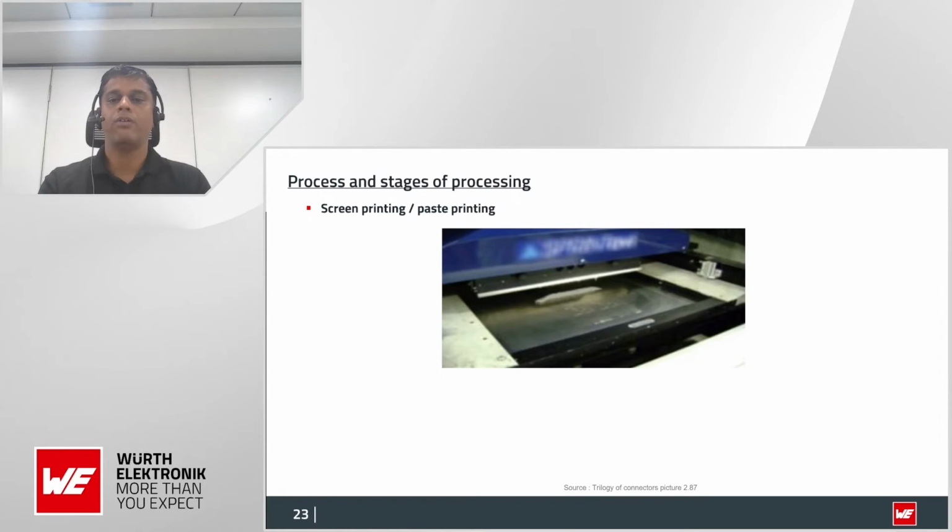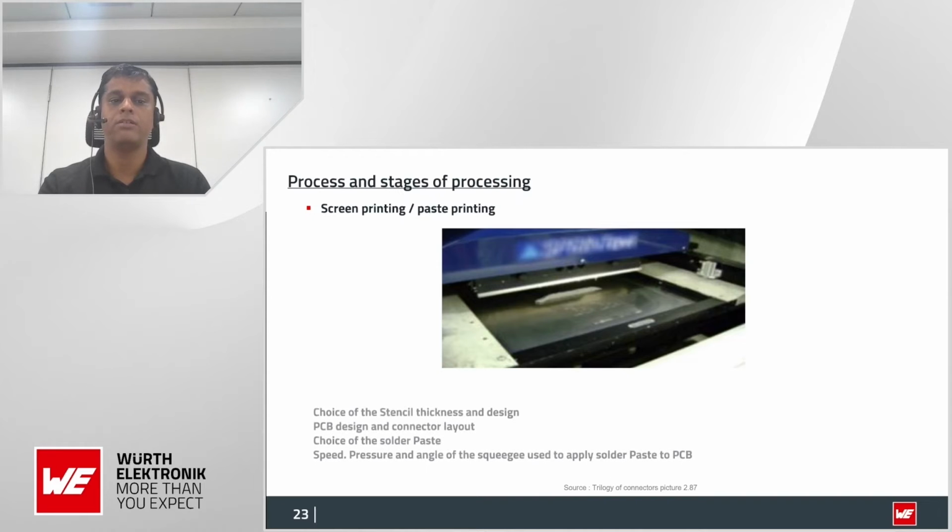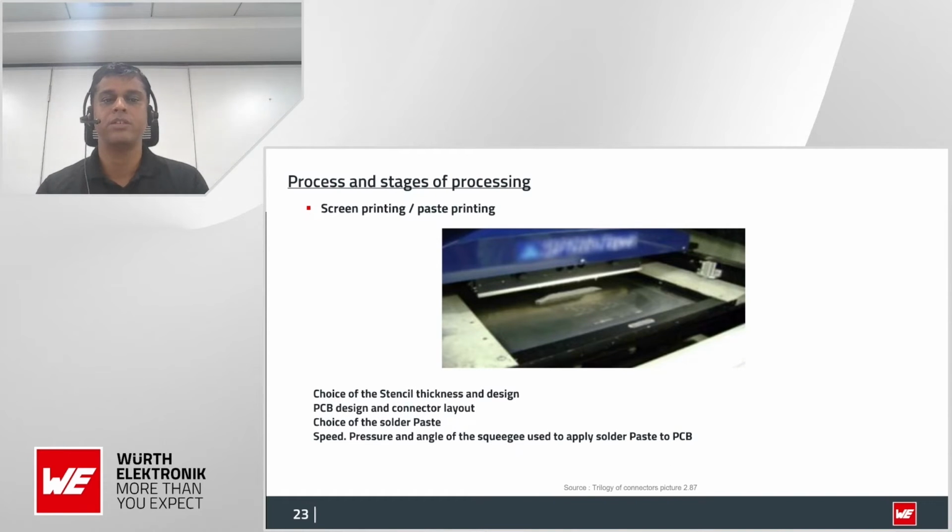And when we have done this, we need to consider these 4 points: the choice of stencil thickness and design, the PCB design and the connector layout, the choice of the solder paste, and the speed, pressure and angle of sequence used to apply solder paste to the PCB.